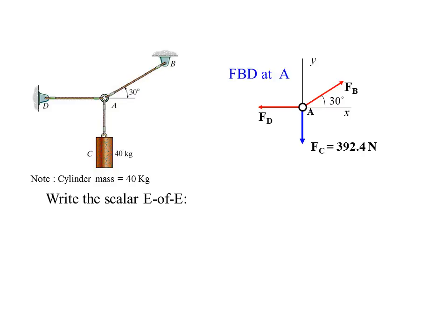To begin to solve for the unknowns, FB and FD, in our case, we're going to need to now apply the equations of equilibrium. For this two-dimensional case, we're just going to remember that the sum of the forces acting on A must be zero, since it's not moving. As F is equal to ma, and it certainly isn't accelerating anywhere, there must be no unresolved force acting on A. So these three forces added together must be zero.